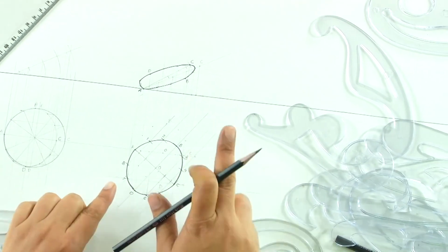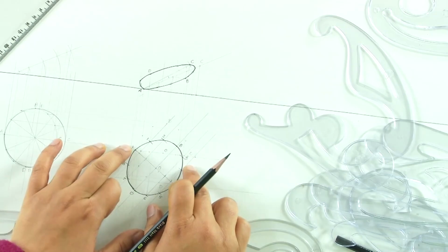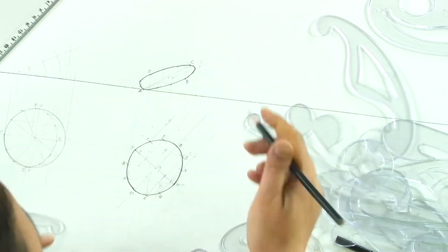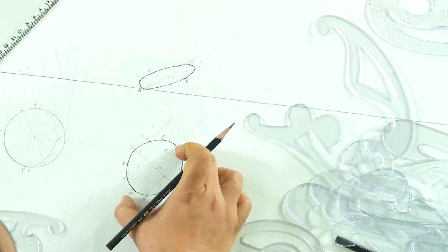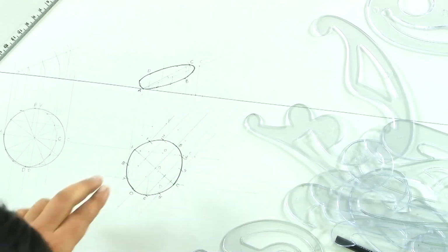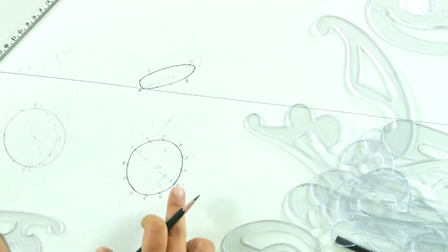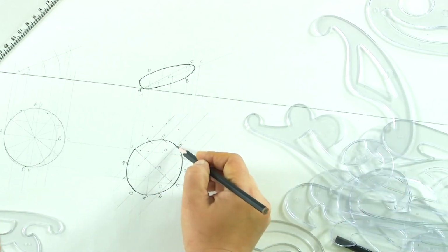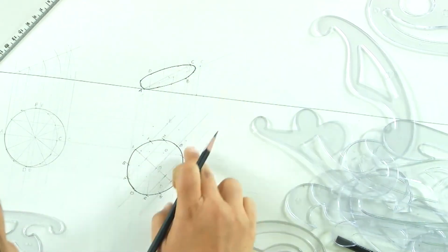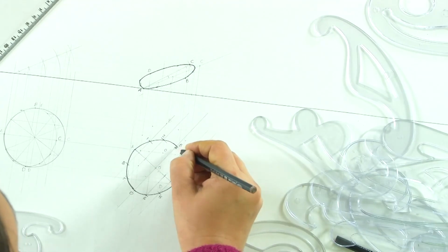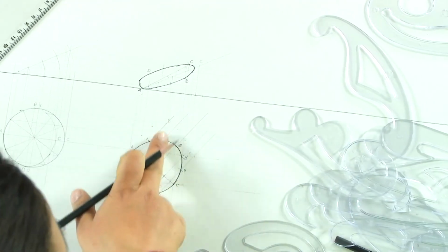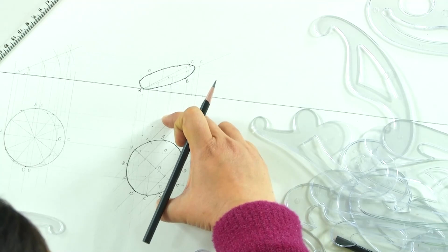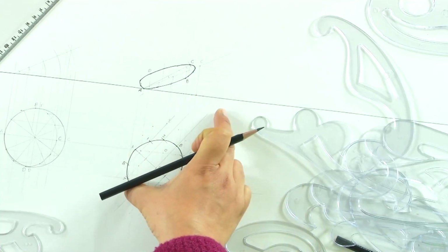Now, the other one was, if we have to make this in such a manner that AC makes an angle of 30 degrees with HP, but the BD makes an angle of 60 degrees. In that case, what we are going to do is, since AC is not changing its angle, the only thing it is doing is the BD now makes an angle of 60 degrees. So, it will still remain the same. The only thing that happens is instead of this BD being parallel, we will now incline this BD in such a manner that BD makes an angle of 60 degrees.